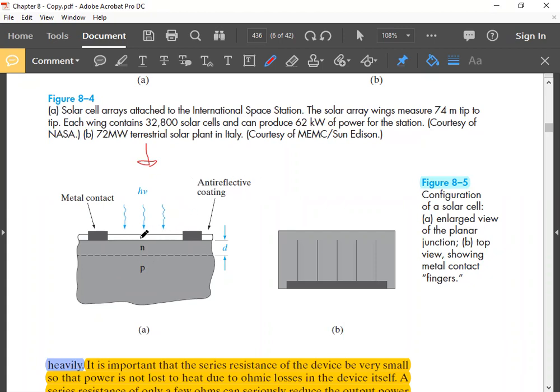And also you have to have some kind of passivation layer. Passivation layer is required. Why? Because this surface, you can see surface of the N region, this surface is equivalent to a crystal defect. I have already told that in previous classes. Surface is viewed or can be viewed as a crystal defect because at the surface periodicity of the crystal is violated. Okay, so whenever there are defects, what happens in the energy band diagram? Anyone remembers?